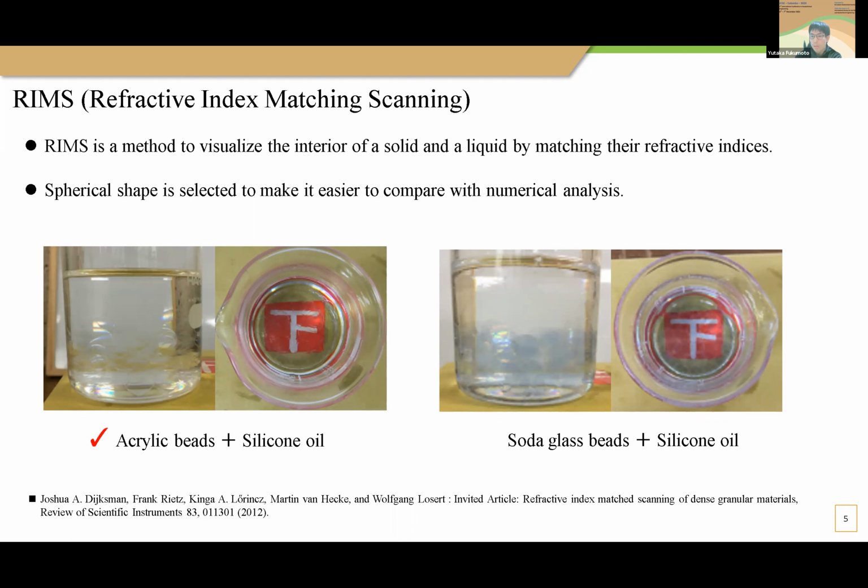As shown in the figures below, the refractive indices of solids and liquids are approximately the same, so making them transparent. In this experiment, we choose the combination of acrylic beads for soil particles and a silicone oil for fluid. Spherical shape is selected to make it easier to compare with numerical analysis.